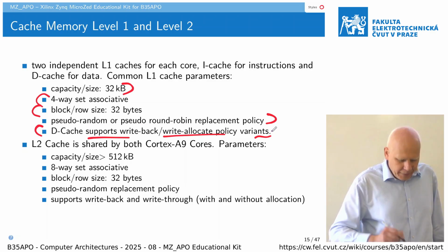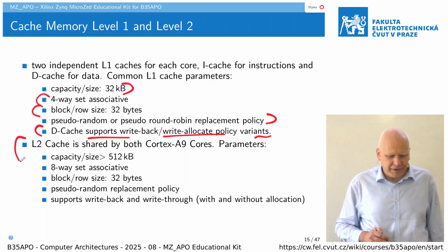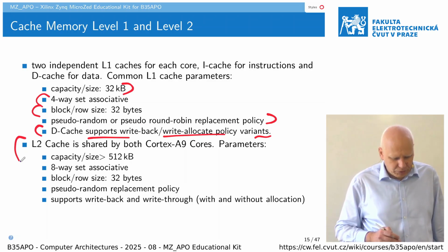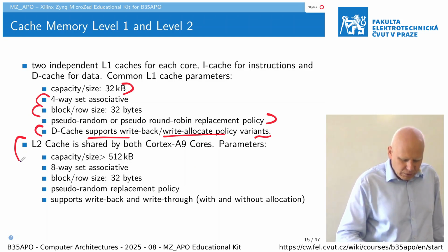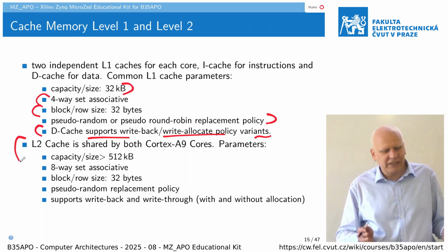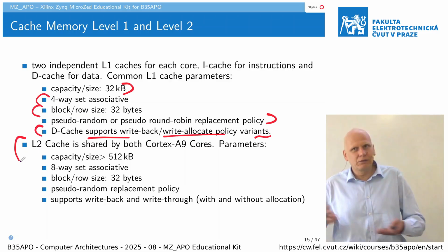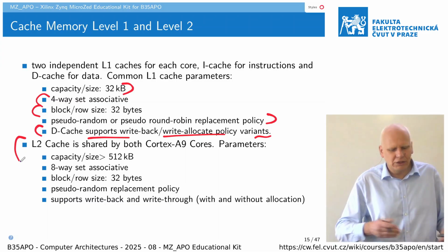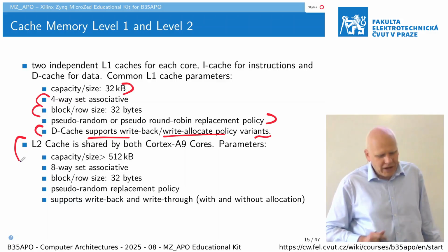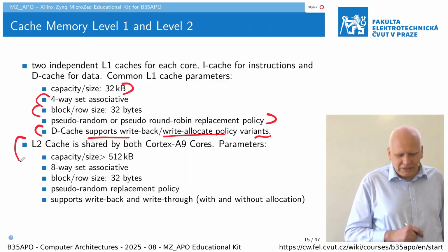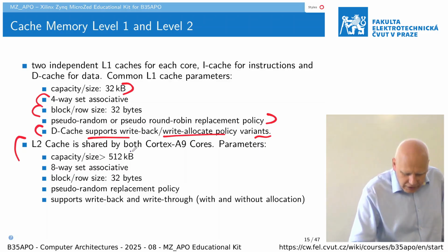And the L2 cache is connected to some coprocessor. I have helped with this support for the RTEMS project on this chip. It is a little interesting how you access and command this cache, because in theory cache doesn't need any maintenance. But at the moment when you have some peripherals and you need to ensure the data are already in the main memory, so that peripherals see those data and so on, then you find that even that simple rule that cache is of no care for the programmer is false.